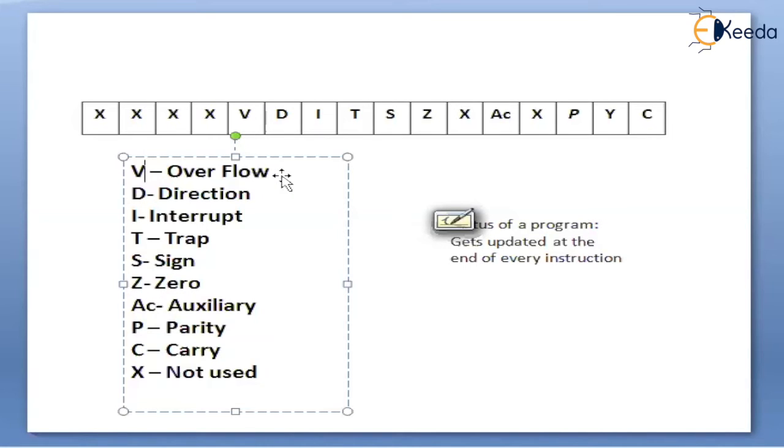We will understand how the sign is going to be reversed accidentally in the next few videos, where we discuss ALU operations. Okay, now the overflow flag will be set to 1 whenever an ALU operation is performed and the sign of the output is different from what is expected. If the sign is unnecessarily, accidentally changed for the output, then the overflow flag will be set to 1.